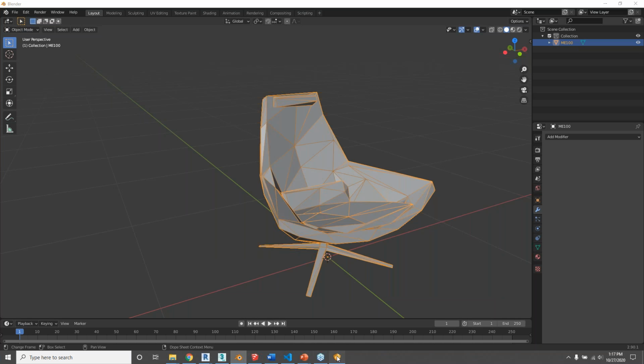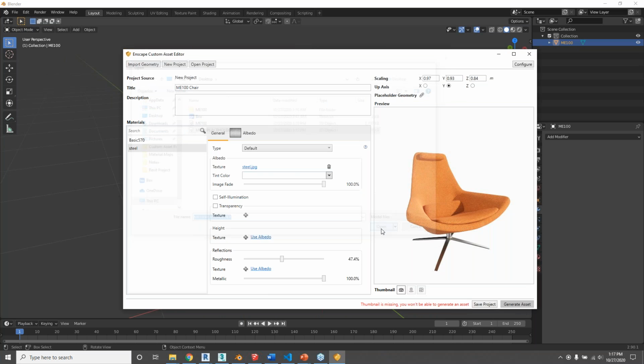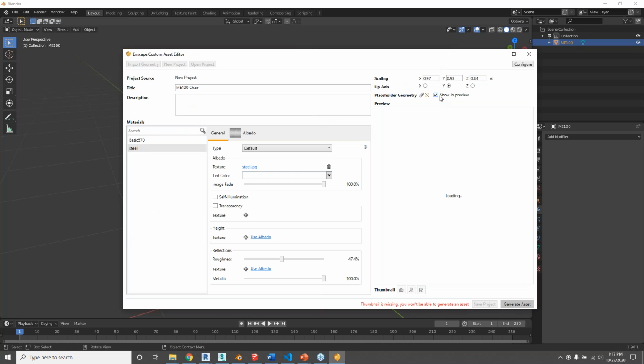and load it up into Enscape. And you can click here to actually see it. By default, it won't show you. And so they're both the same orientation, same size, so we're good. If you load this in, by the way, it might look really weird, like there might be dark splodges on it. You don't really have to worry about that because that doesn't really translate to any of the like Revit or SketchUp. That weirdness is left behind in this editor.